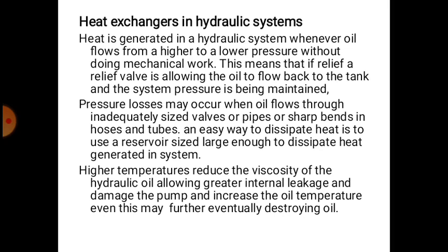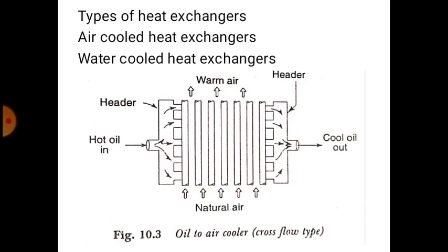An easy way to dissipate heat is to use a reservoir sized large enough to dissipate the heat generated in the system. Higher temperature reduces the viscosity of the hydraulic oil, allowing greater internal leakages, damaging the pumps and further increasing the oil temperature, eventually destroying the oil.